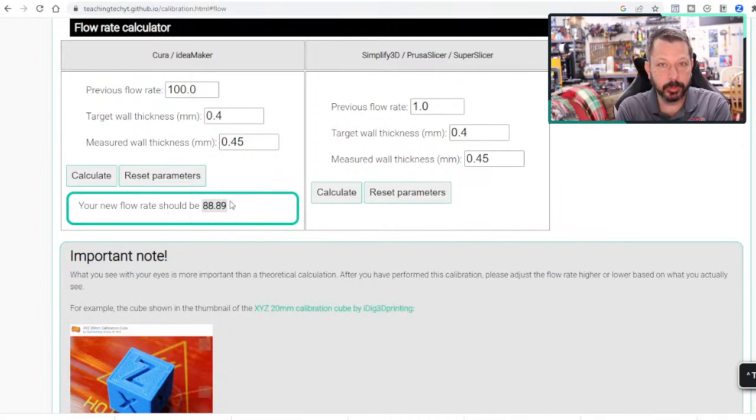You know, like two walls side by side, or a top or a bottom, because it's going to cram together and you get ripples in the surface or bulges on the outside or whatever. And so I don't want too much filament in a single location. It's going to obscure details or make the print just bad.